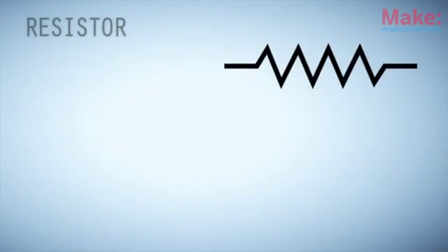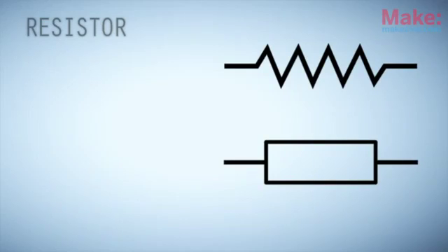That covers what a schematic is and what all those lines all over the place are. But what about all these component symbols, eh? What's up with them? Well, there's several you're most likely to run into. A resistor's symbol usually consists of a single zigzagging line. It's also sometimes represented as a simple rectangle with a terminal lead at either end.